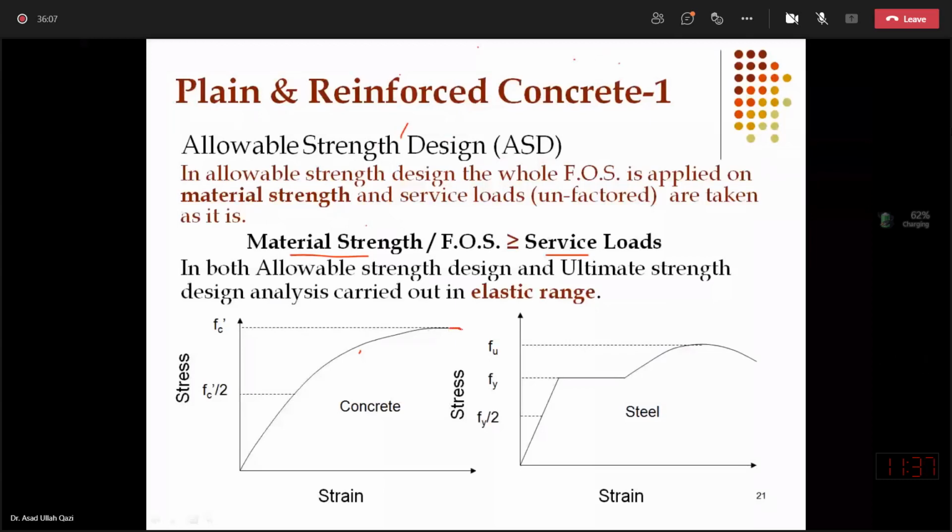you will use, and full material strength, like if concrete will soften here and it will get to this part after attaining post peak, 85% of its peak almost up to this branch, this full material strength of concrete and yield up to yield of steel. So up to this limit of concrete and steel, you will utilize in USD, not like ASD, where you use almost 50% of the material in concrete. In USD, you will utilize full material capacities. So material in the inelastic range, particularly concrete capacity, full material capacity will be used, and area under this curve will be calculated under USD.